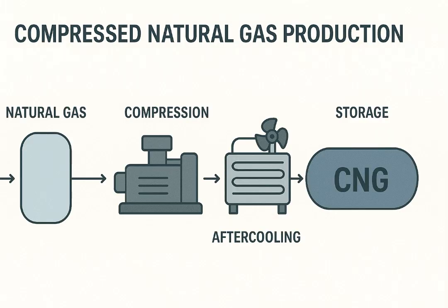7.3 Production of compressed natural gas, CNG. CNG is natural gas with more than 80% methane in composition, which is stored at high pressure, typically around 200 to 250 bar, 3000 to 3600 psi. This compression reduces the volume of the gas, making it feasible to store and transport it more easily, especially for applications like vehicle fuel and gas supply.